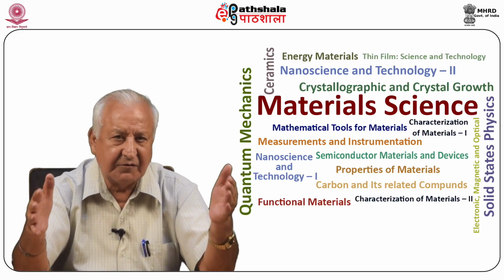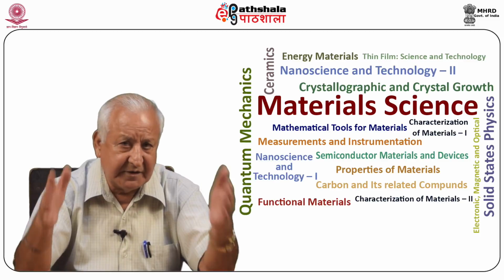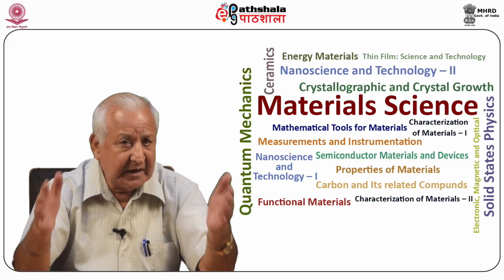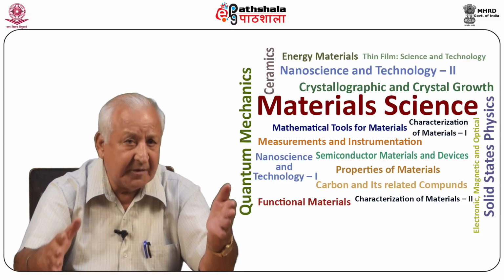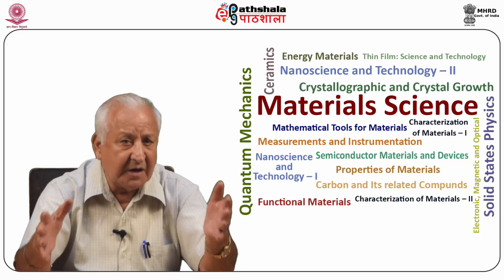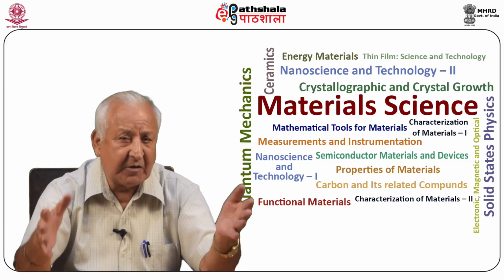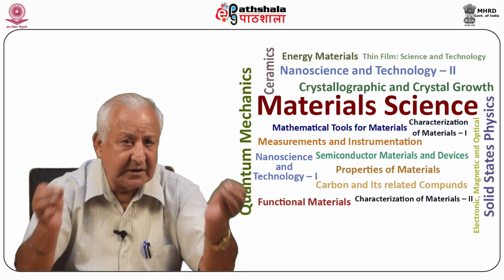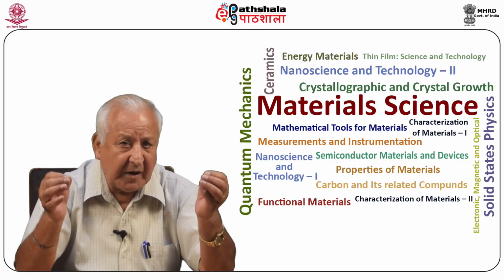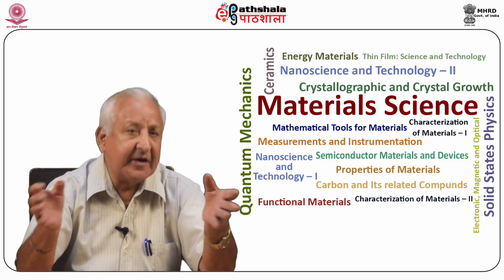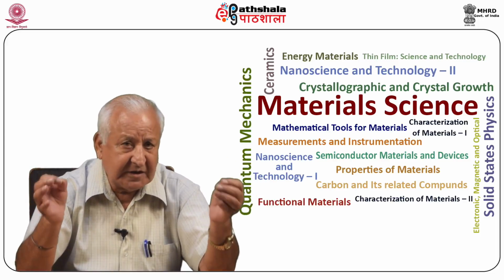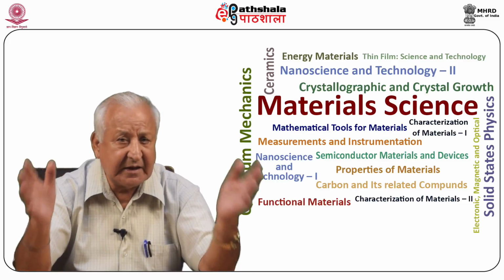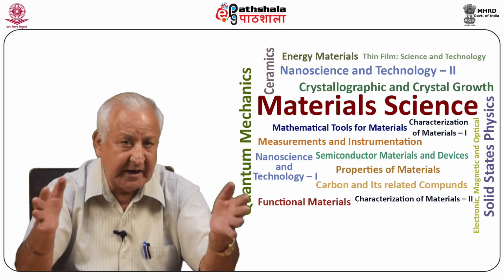Now let us summarize what we have learned. In this module, we have discussed slip, motion of dislocation, and dislocation density. It is explained that the plastic deformation in crystals can be due to a large number of dislocations sweeping across the slip planes. On application of stress, the dislocation experiences force per unit length, which is given by F equal to tau b. The concept of dislocation density is also given, and it is explained that it has the dimensions of inverse area.